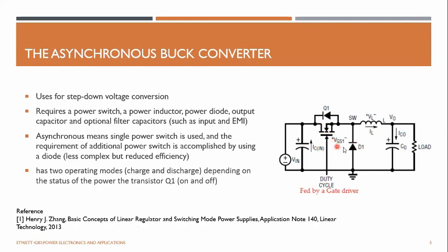But it adds more complexity. You have to switch both these two MOSFETs based on these square wave pulses, so you need to handle some dead time. You can't switch them simultaneously. You have to deal with some dead time between these switches, so it will add more complexity. So if you need a very simple design, you can just use a diode. That will reduce the complexity rather than going with two switches.